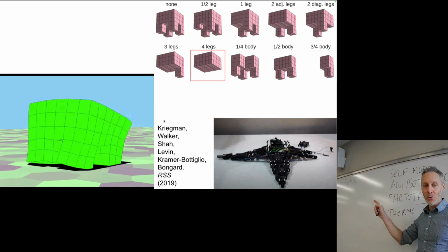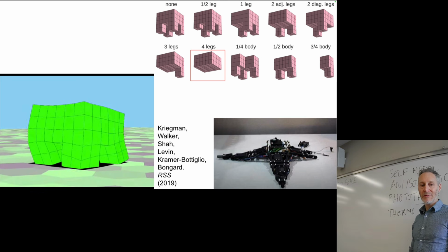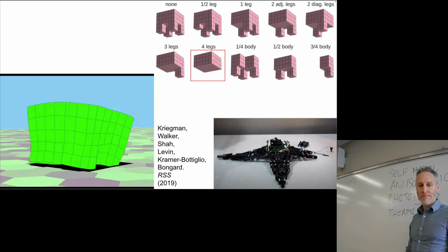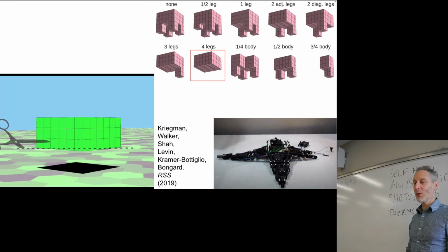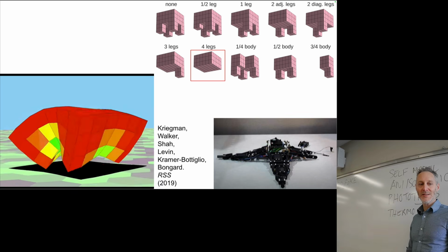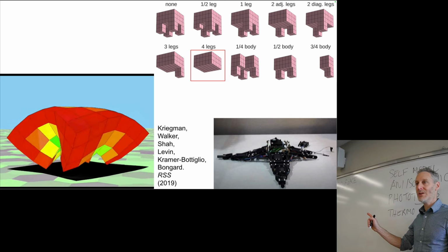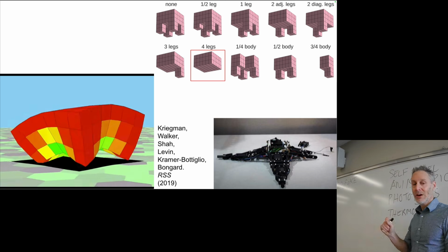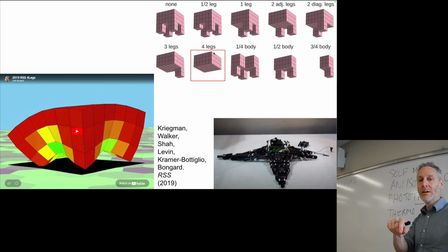So here's a controller evolved for the intact robot. In a moment, you're going to see us cut off all 4 legs. After we cut off all 4 legs, the evolutionary algorithm evolves a compensating controller and comes up with this. This is another thing that soft robots can do that rigid robots cannot do. Rigid robots, by definition, cannot change their morphology. They cannot adapt their morphology. All they can do is adapt their controller when unexpected things happen.